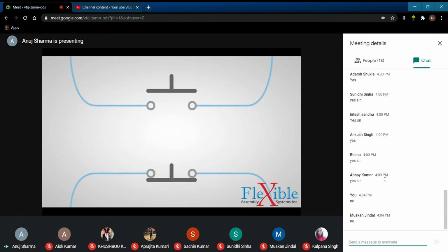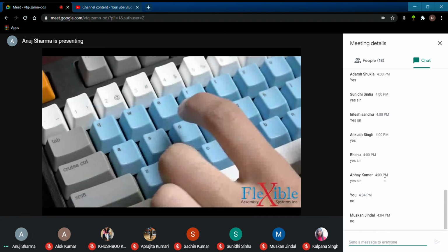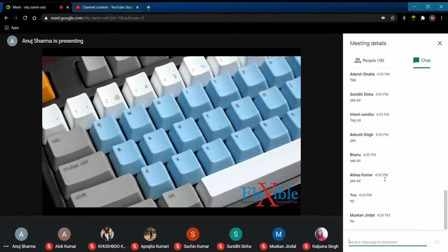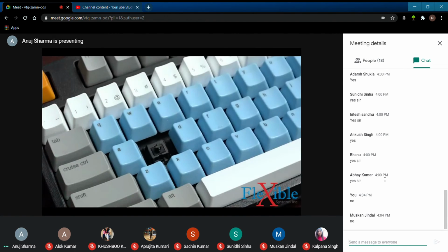Momentary switches are sold with an output of normally open or normally closed. This refers to the default state the switch will be in when it isn't actuated. When purchasing an inductive proximity sensor, you must choose between normally open and normally closed. Think of the letters on a keyboard. Each one of them is a momentary switch, and its normal state is open. Only when that key is pressed will the state of the switch change to closed. Immediately after releasing the key, it will default back to its normal state of open. You don't have to press each letter twice to toggle it on and off.